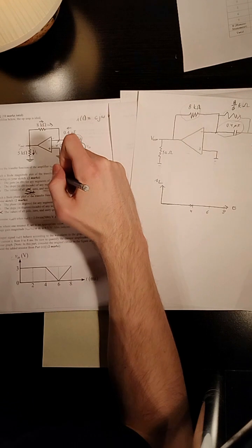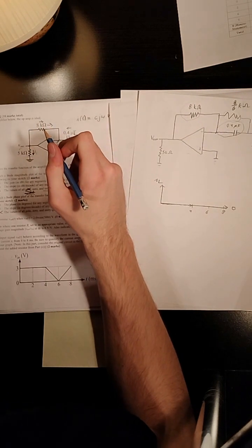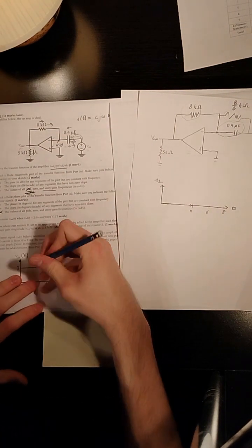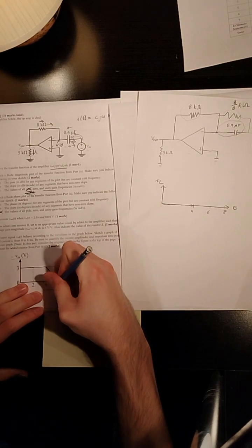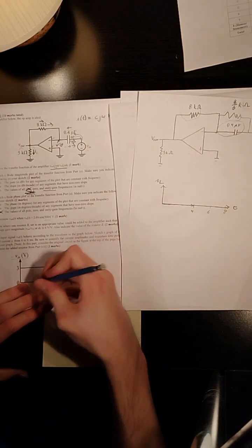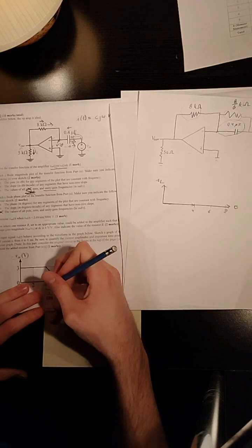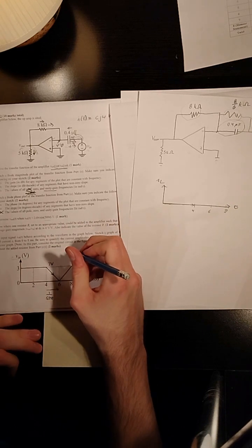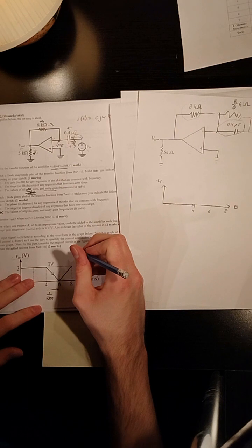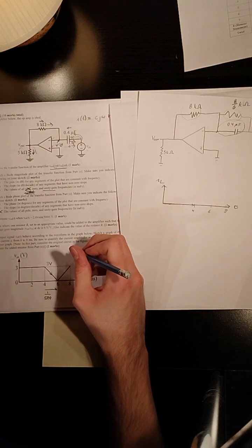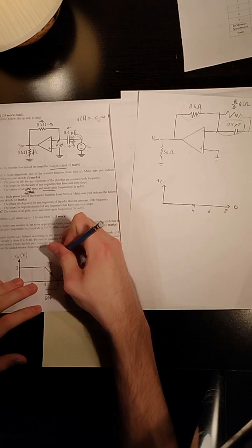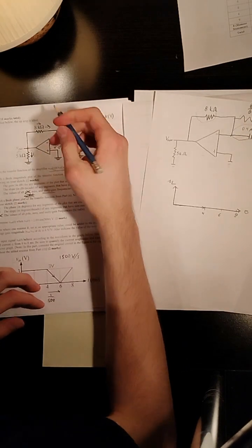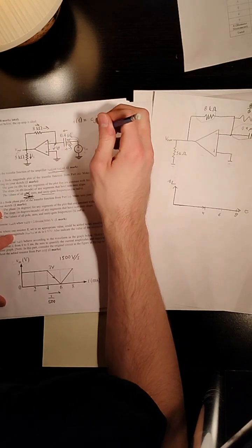So your voltage, V out, in this case, would be, okay, so this slope here, so this is 2 milliseconds, or 1/500 of a second. And your change in voltage is 3 volts. Which means that your rate of change is 1500 volts per second. If you were to plug this into the capacitor equation, you would see that